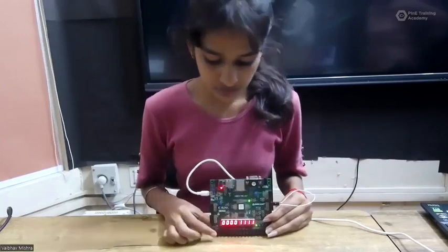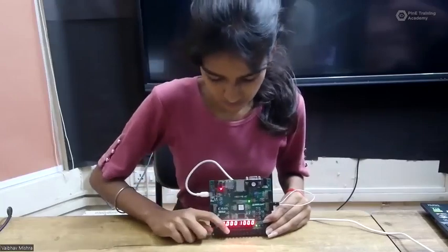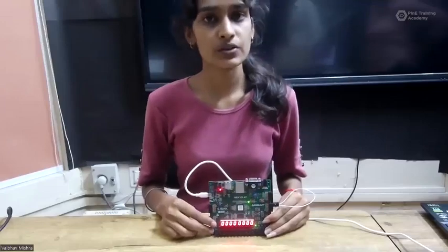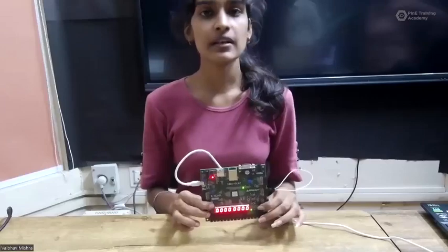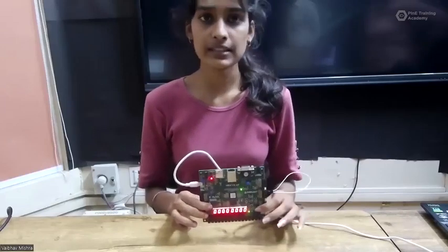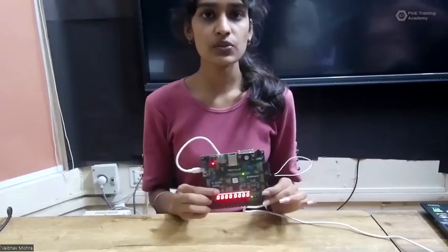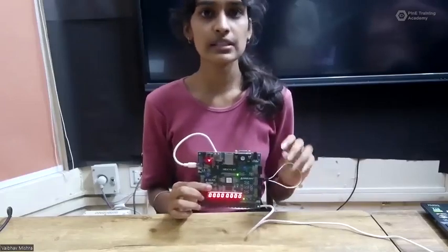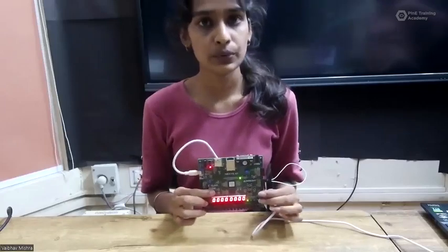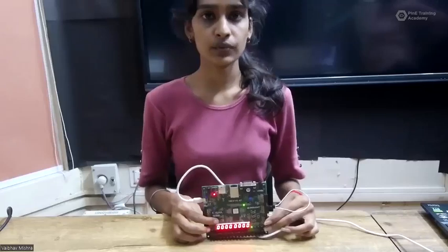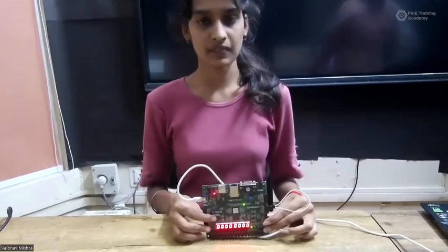Now, if I change the input pins, like making some of them zeros, our received output also changes. So in this single FPGA, the module works as both transmitter and receiver. Therefore, we call it a transceiver. This transceiver is based on serial communication through the serial communication pins of PMOD, and this serial communication is based on the UART protocol. So here's the complete demo of our project, UART communication transceiver using VHDL coding. Thank you so much, everyone.